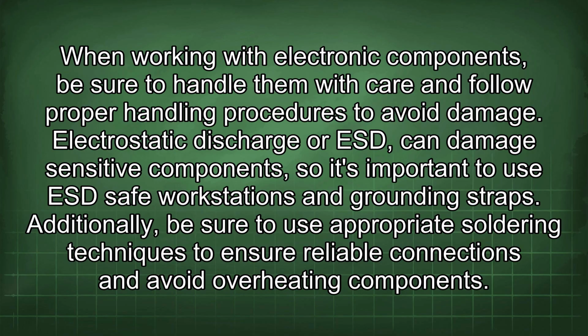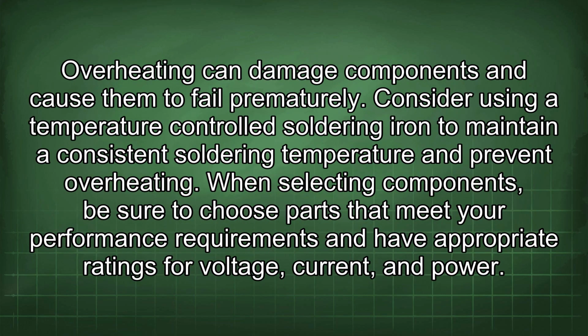When working with electronic components, be sure to handle them with care and follow proper handling procedures to avoid damage. Electrostatic discharge, or ESD, can damage sensitive components, so it's important to use ESD-safe workstations and grounding straps. Additionally, be sure to use appropriate soldering techniques to ensure reliable connections and avoid overheating components. Overheating can damage components and cause them to fail prematurely. Consider using a temperature-controlled soldering iron to maintain a consistent soldering temperature and prevent overheating.